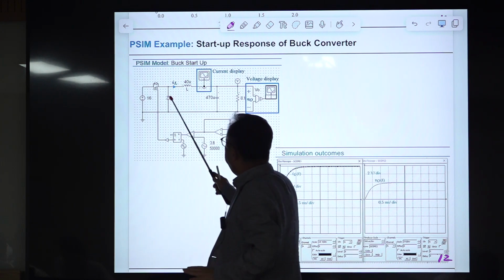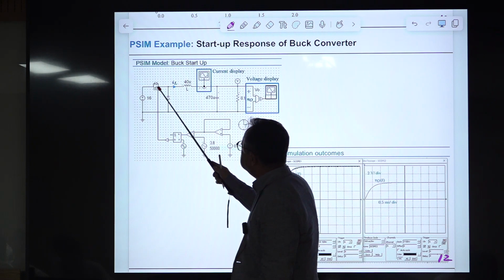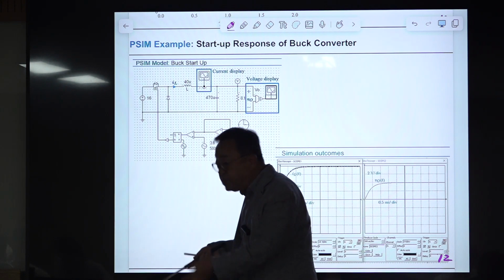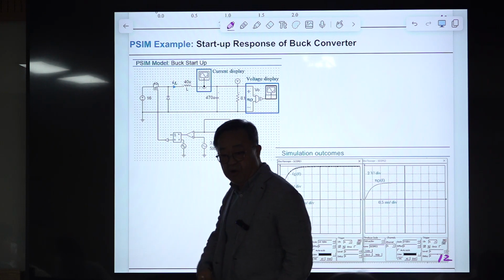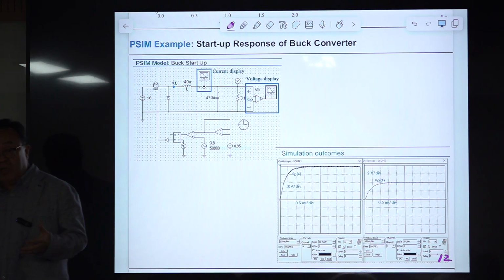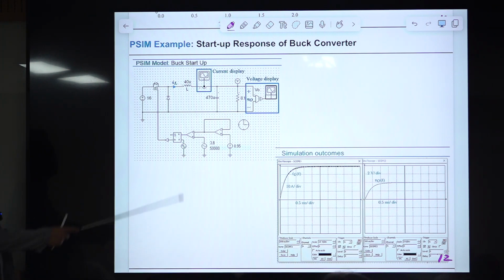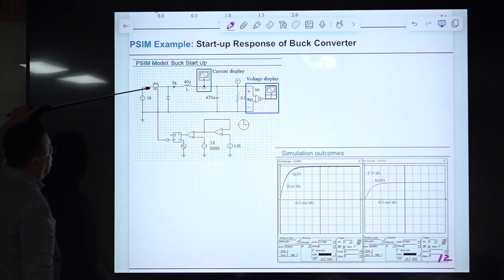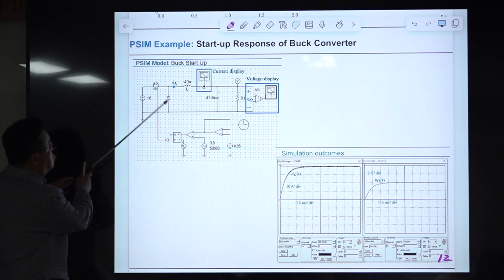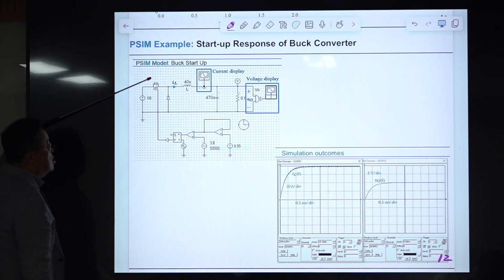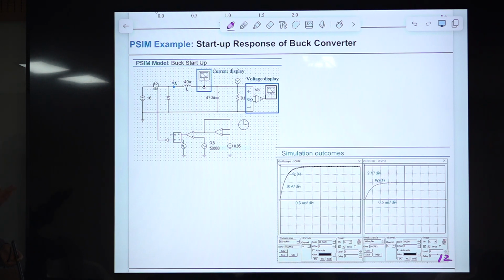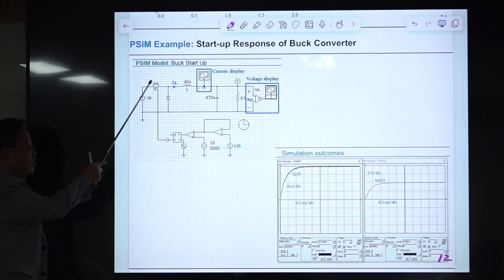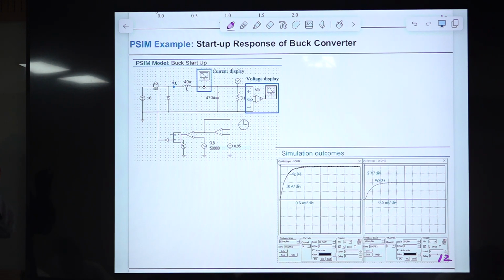So to make this thing applicable, usable for the practical purpose, we do something during that process. This diode is created unintentionally. This is the byproduct, so they come all together. So this is called an anti-parallel body diode. The name is because usually the current is flowing from drain to source, this current flow direction, and this diode is opposite to that direction. So this diode is reverse biased all the time for the PWM converter. So this diode is not doing anything, but there is a diode.